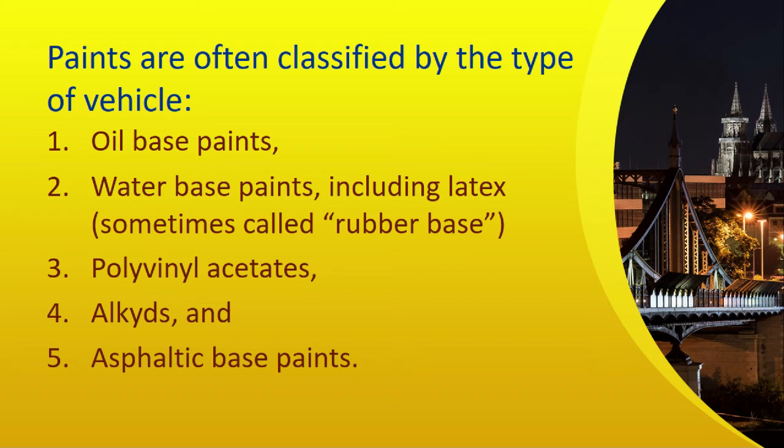Paints can be made mildew resistant. They can also be made to chalk. Some enamel paints have a high gloss. Flat paints are just the opposite. Their surface is dull or non-reflective. Some paints are more or less all-purpose and can be applied over wood, metal, plasterboard, or masonry. There are special kinds of paints for floors, for masonry, for exposure to saltwater spray, and for metals. Some paints, like those with an asphaltic base, are good for waterproofing.